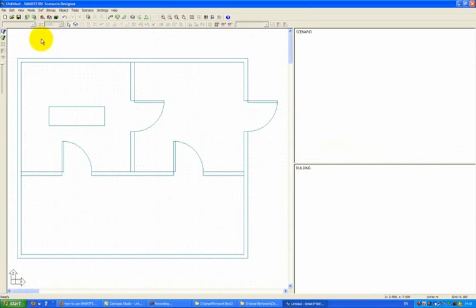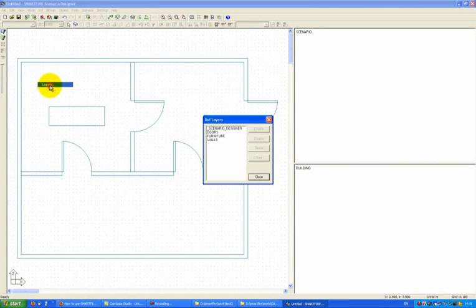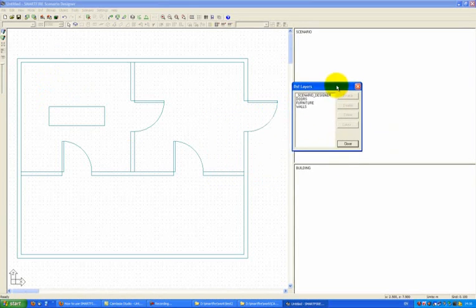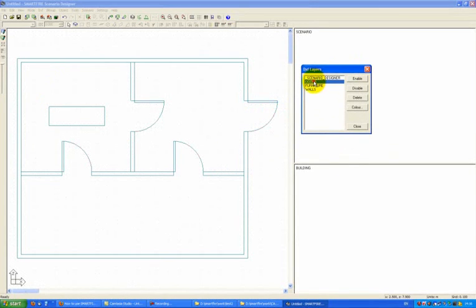The first thing to do with a DXF file loaded is to check out the layers. We go to the DXF tab on the menu and select Layers. You can see the contents of all the layers that are available. When you select them, they get displayed in pink. And in terms of using the automated tools within the Scenario Designer, we want to disable the doors. Therefore, human interpretation, they don't help the software to locate doors, so we can disable them. They then go to grey.